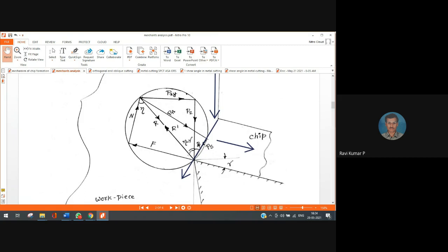You may observe the angle beta, the shear angle, here. I am observing another angle eta, which is nothing but my friction angle. I may observe the rake angle gamma. Of these, some are applied by you and some are formed automatically. Observe, gamma is an angle which comes from grinding the tool with a particular slope, right? So beta is an angle which comes on its own.